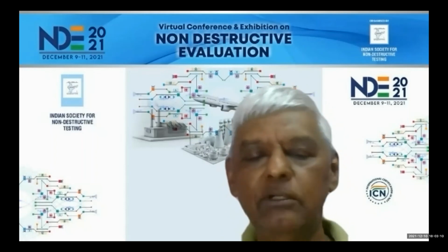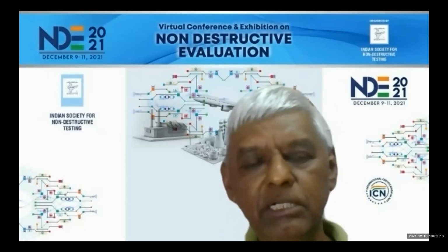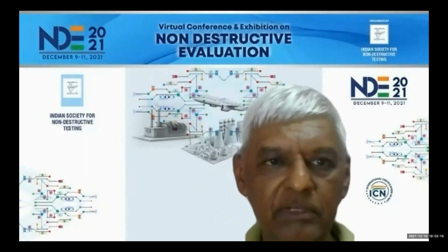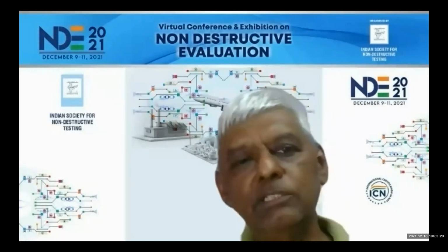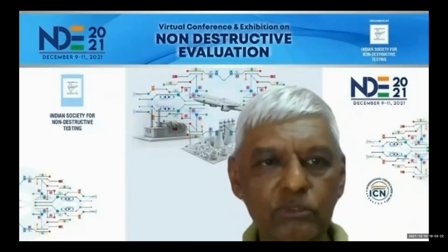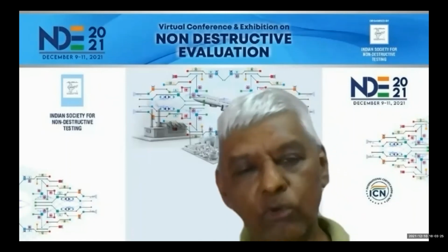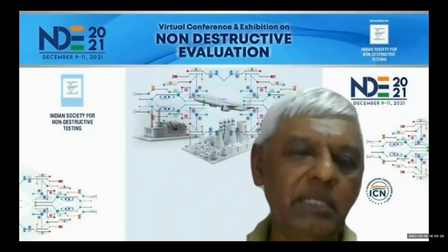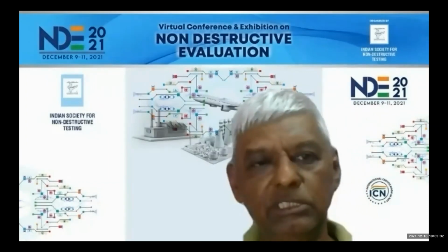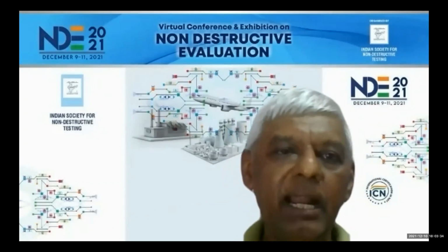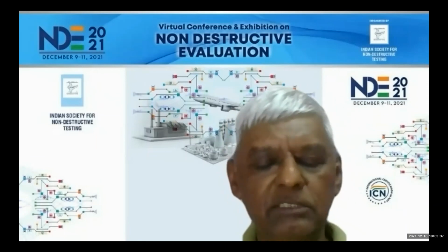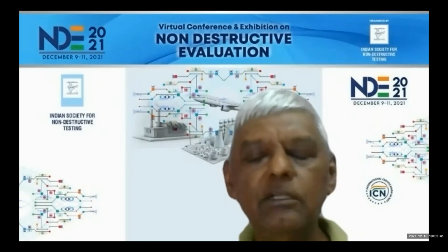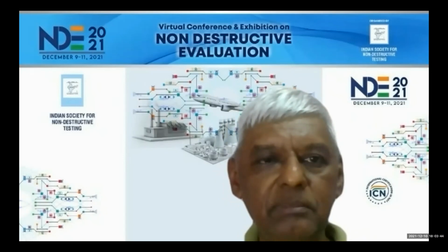So again, going back to my standard example of a wind turbine, what we have been doing till now and are continuing to do is that we send a person up tower. We call it up tower inspection. The guy has to climb up that tall tower. No, there is no lift or anything. He has to climb. Then he goes outside onto the hub, and sometimes the blade is kept in a horizontal position, and then he will climb onto that, and with of course harness and safety measures, he will be doing all the inspection, and then at the end of it, you will realize that there is nothing wrong with that blade.